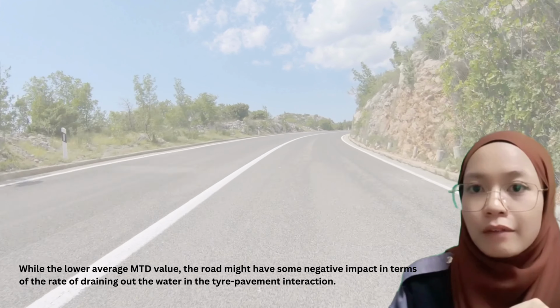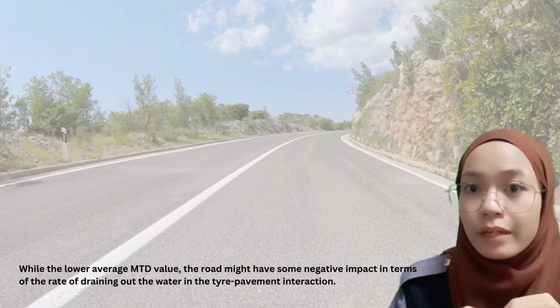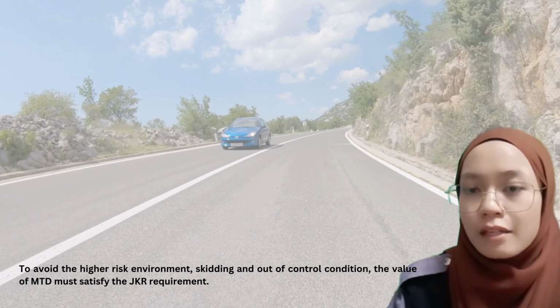While for a lower MTD value, the road might have some negative impact in terms of the rate of draining out water in the tyre-pavement interaction. To avoid the higher risk of skidding and out-of-control conditions, the MTD value must satisfy the JKR requirement.